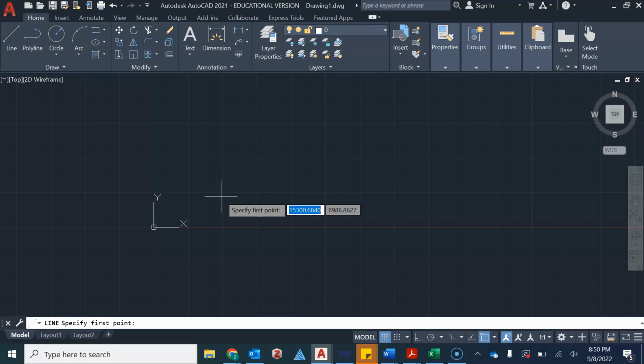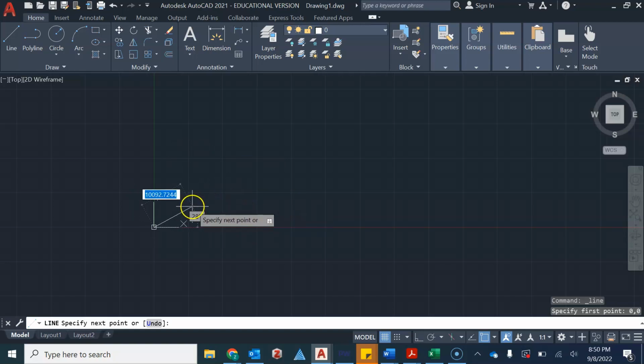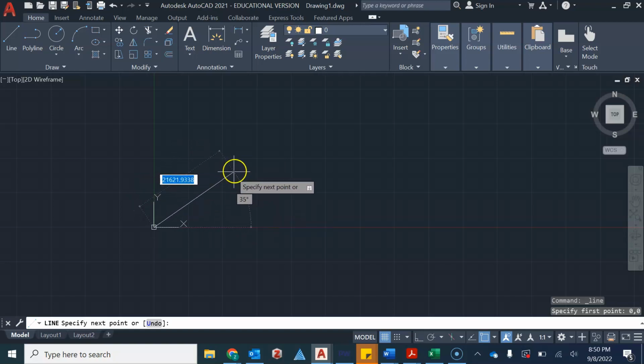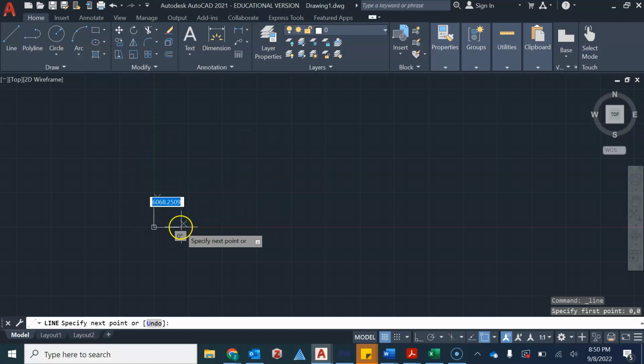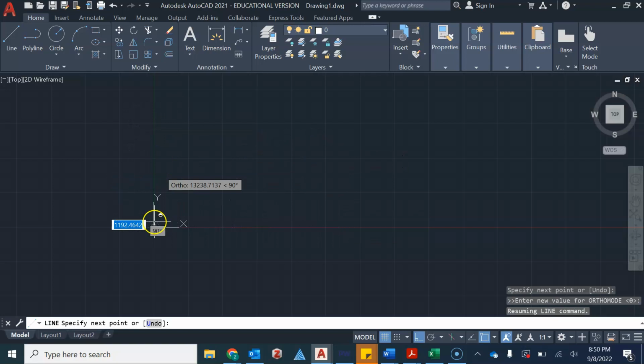You probably experienced something like that in math class. So I'm going to type in 0, and to move to the other window, you hit the tab button and hit 0 again. If you hit enter, it's going to lock you in at that origin point. At this point, you could specify a certain angle, as you can see here. You can also specify the length of the line. You could go any direction you want. If you hold down shift, it'll lock you in on the vertical or horizontal axis, so it basically creates that 90-degree angle for you. Just some things to really think about there.